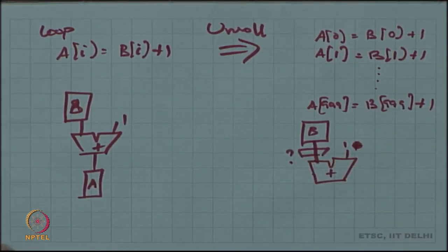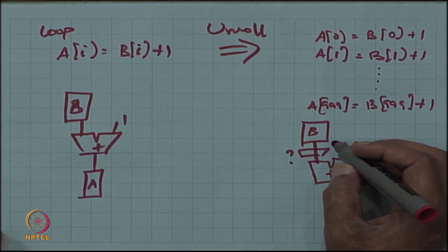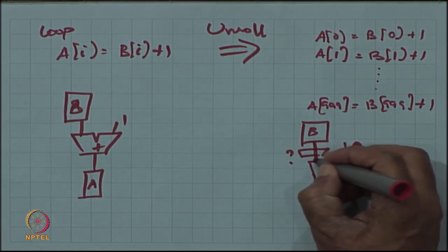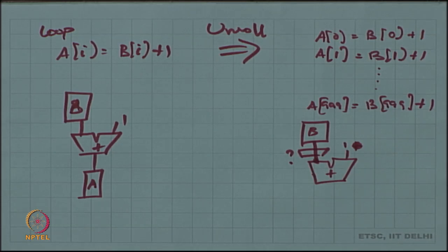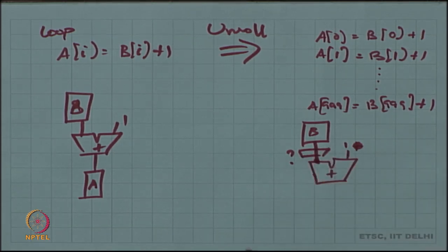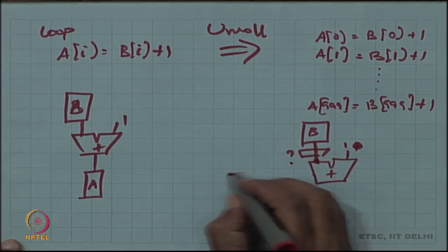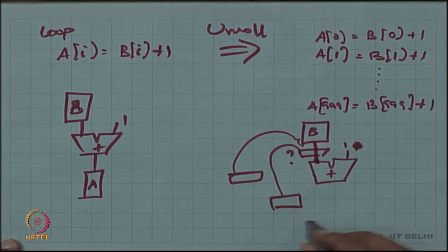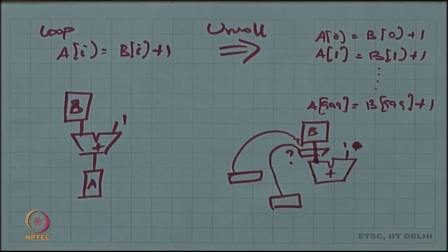Inferring the width of that mux is not obvious just from here. It depends on how many independent paths are there from different sources to that particular input of the operand. In this extreme, actually there was even no need for a mux, but if there were some registers, all of which somehow at different stages in the schedule had their outputs routed into the adder, then there would be a mux over there.